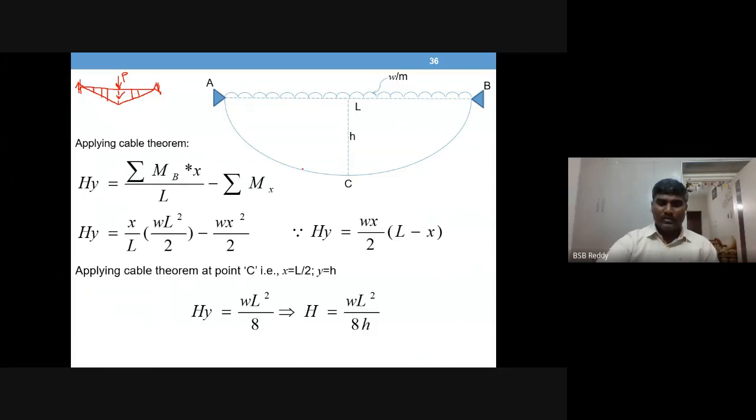Whereas here, the cable subjected to UDL is going to deform in the form of a curve. So if you know the sag value somewhere, to find the value at other locations, the simple linear relation is not sufficient. You should know the nature of this curve. Then only it is possible. Means what?